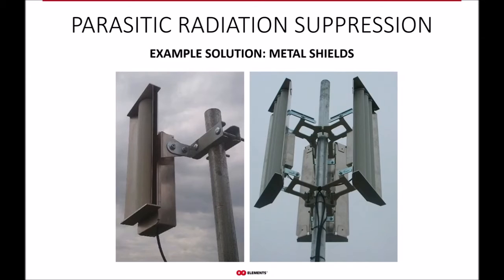One of the ways manufacturers try to deal with the azimuth side lobes are various shields and shrouds that are attached to the back of the original antenna structure. Be it the aftermarket kits or the shielding kits provided by the manufacturer. So what is the effect of these shields on the radiation pattern of patch arrays?